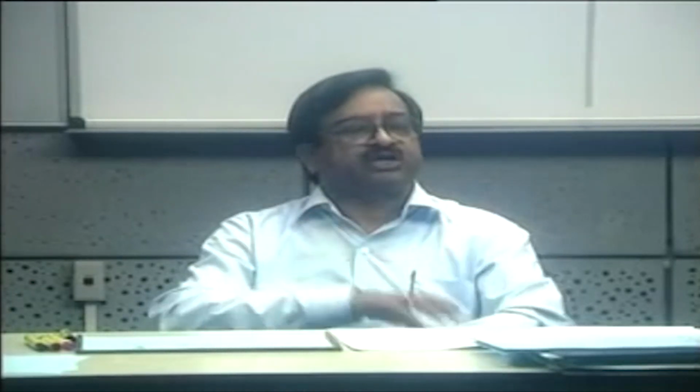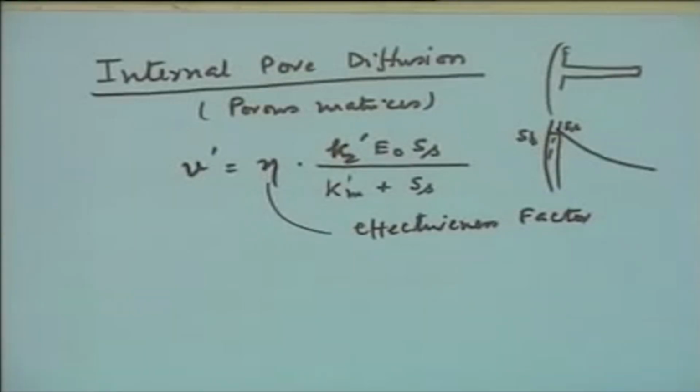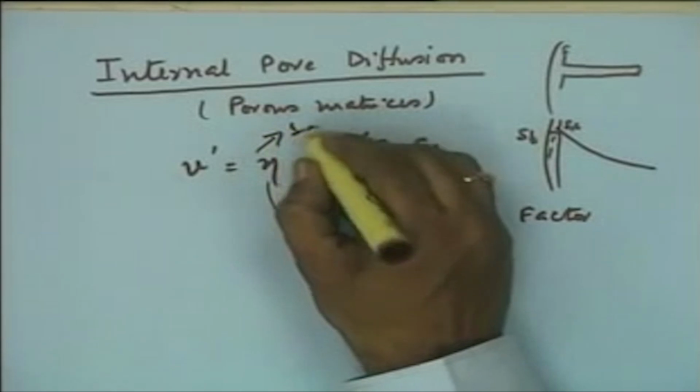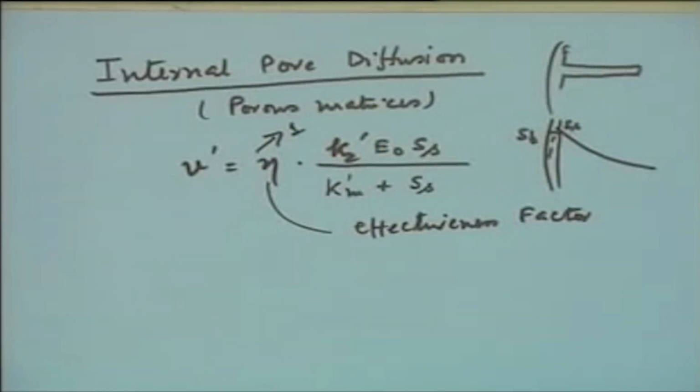And usually in most cases, as per experimental experience, a particle size of about 30 microns in most biochemical reactions has been considered to give an effectiveness factor of 1. Essentially, you will see from this relationship that the maximum effectiveness factor can be 1, because that means you have the enzyme reaction rate under conditions when the whole enzyme particle is flooded with substrate.